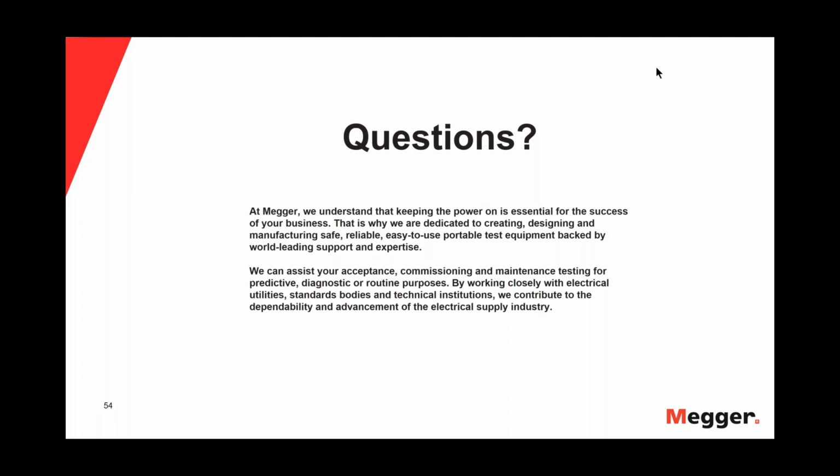One common problem that I sometimes see in the field is that people see a very distorted trace and they don't know what to do with it, and then you realize, wow, the cable is 3 miles long or 5 miles long, and their range, the distance that they have on the screen, is only a few hundred yards or something like that. So they don't even see the full trace. So the most important adjustment is the X range, as it is called with our TDRs. You want to have a minimum of 5 times the cable length to actually see that transient, that traveling wave.